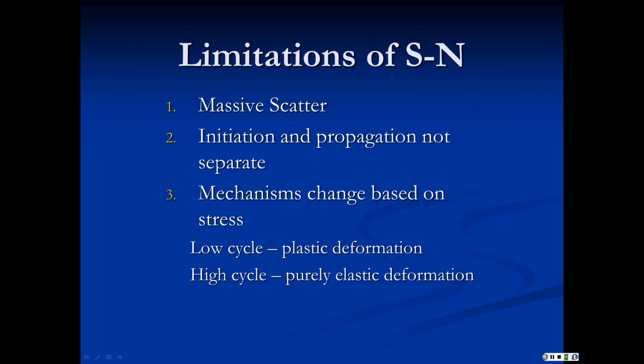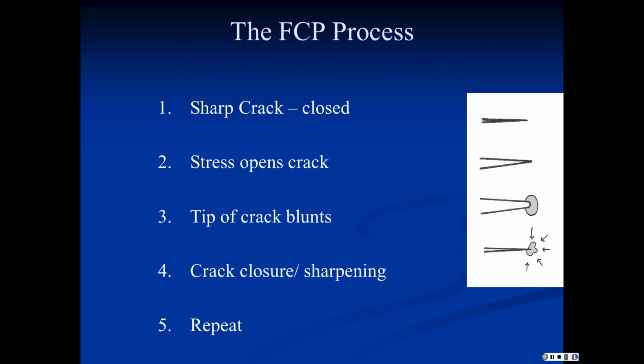It doesn't separate out initiation and propagation, and the propagation is part of the life we're measuring in the number of cycles to failure, but we don't know what that is. So there's a little less understanding of what's happening. We have a problem in that SN doesn't particularly work in low cycle fatigue because of the plastic deformation, and we don't have a good tool for that. And in high cycle fatigue, obviously, it works reasonably well, but it doesn't handle the transition between these at all. So it's less than perfect, but it's fine for probably 80%, 90% of the engineering that you will do as a machine designer or as a structural engineer.